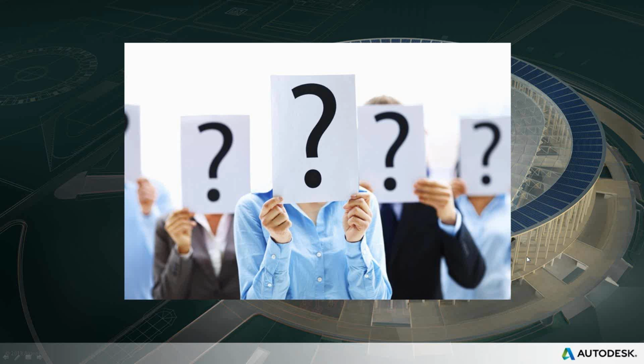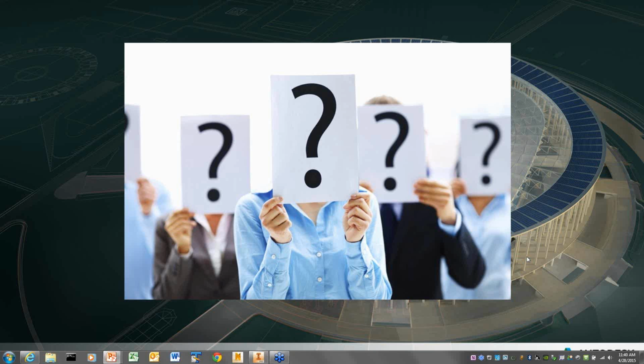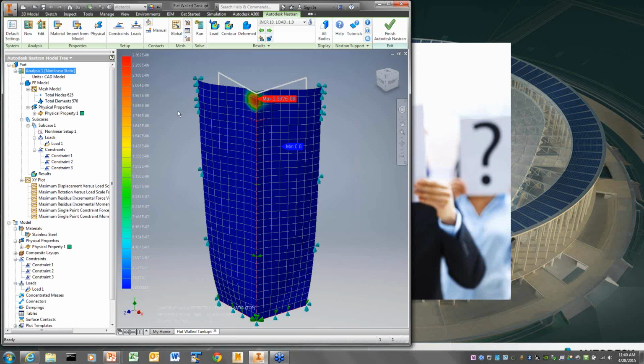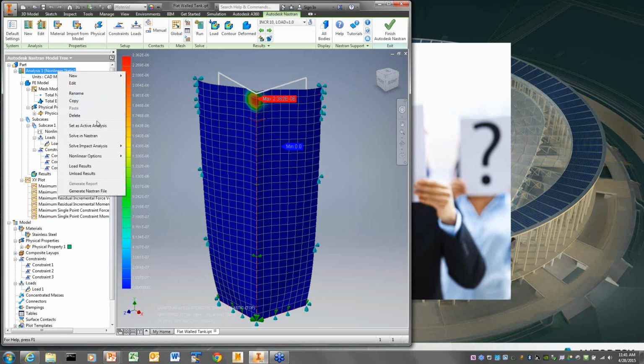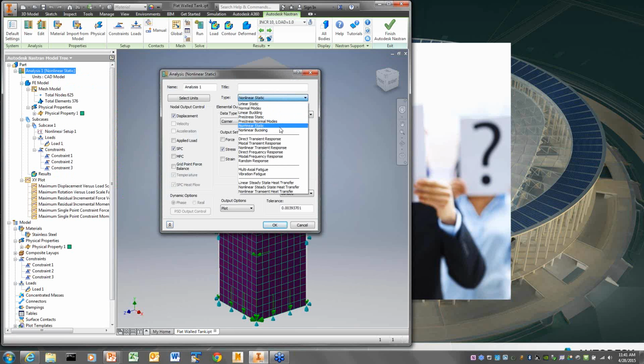So we had another one from Daniel here. I was wondering, how does he model a ball impact? So I think we would use the impact analysis feature. I don't know if you could bring up Inventor, Bart, and we could just take a quick look at that. Yeah, there's two ways. If you're going to do a ball impact, there's two ways you can do it. One is to manually set everything up, and it would be a nonlinear transient analysis, which is down here.